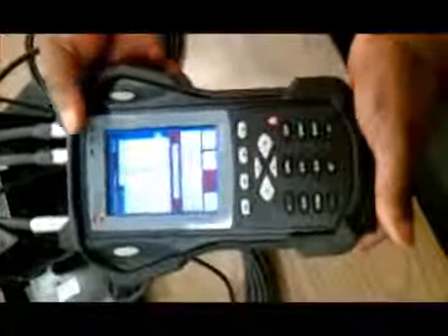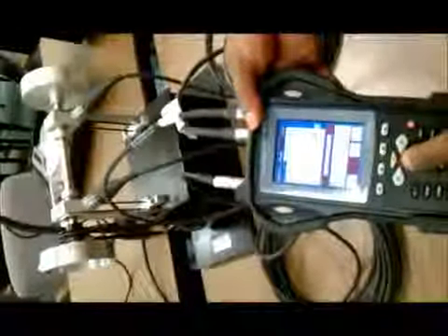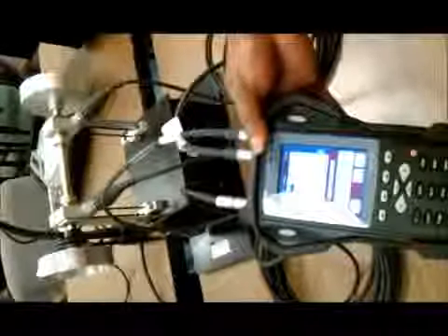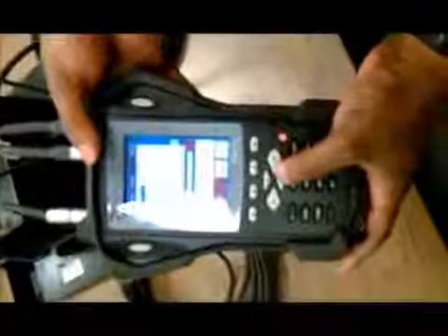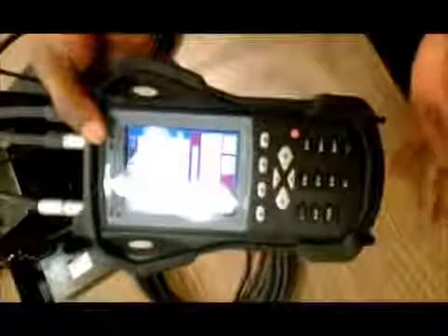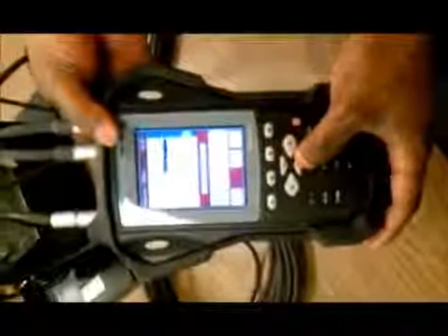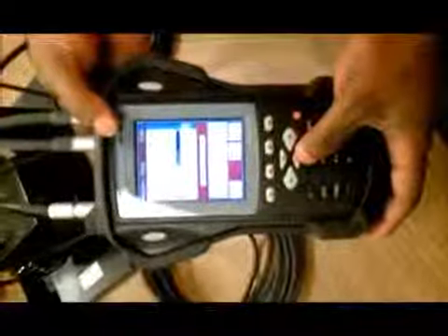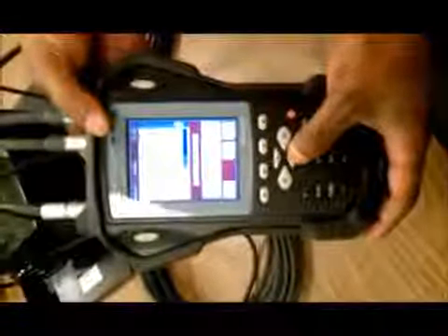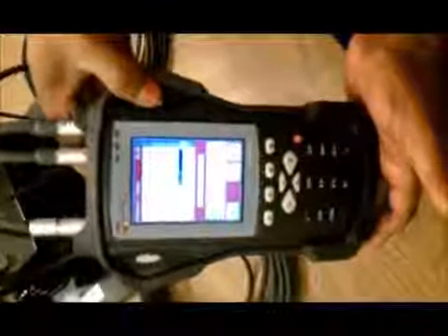This right here allows you to set up what type of sensors you have. In this case we have accelerometers. What the sensitivity is that we want it at. For now we have 100. We also have the option of setting up what type of units we want to see on the y-axis. We have our acceleration in G's, acceleration in meters per second squared, inches per second, millimeters per second, vibration micrometers, and mils, along with time and ESP. We'll use mils for this one since that's what a lot of the companies use.